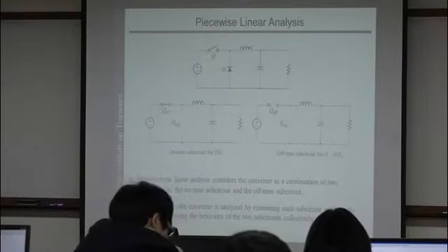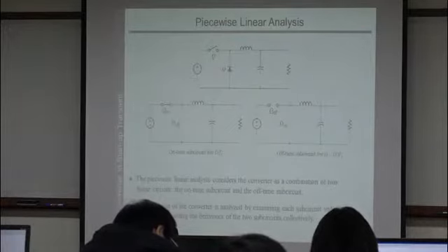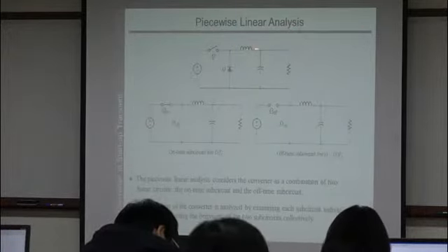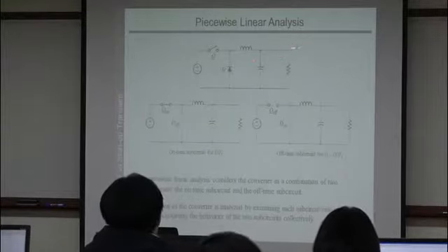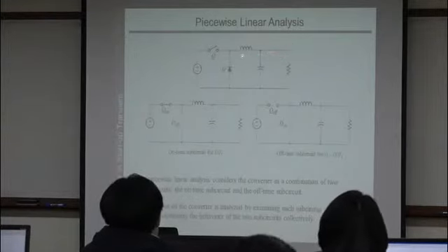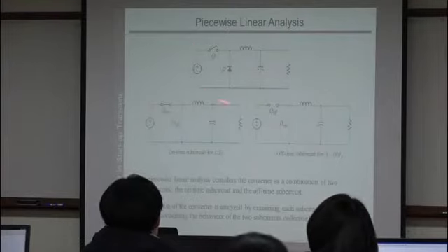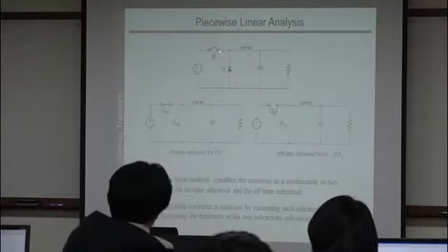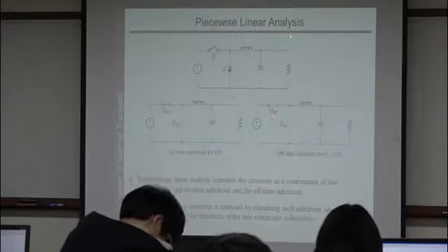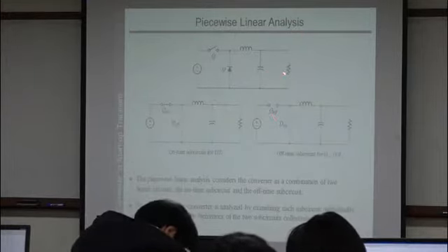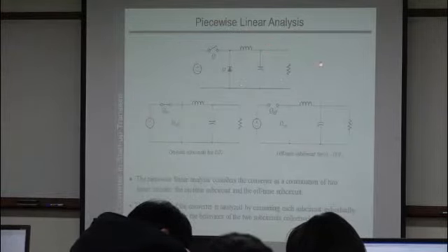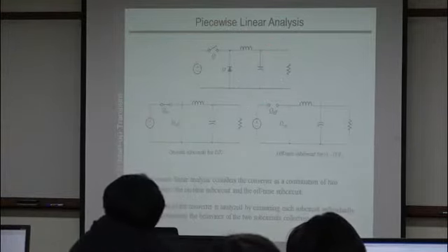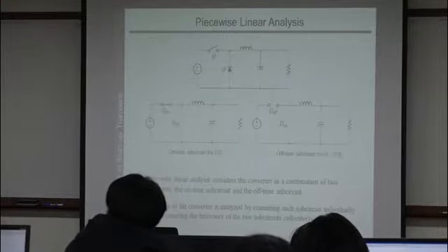Then let's discuss the piecewise linear analysis. Okay, the piecewise linear analysis technique is very, very popularly used in circuit analysis. And here you have a simple buck converter, and this circuit has 2 states, right? First, when the switch is turned on, and second, when the switch is turned off. So the piecewise linear analysis is the technique where you separate the circuit case by case. Then finally you just sum the results. Then you can get the circuit's steady state operation.